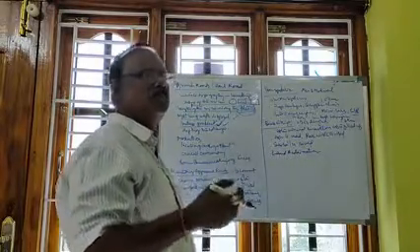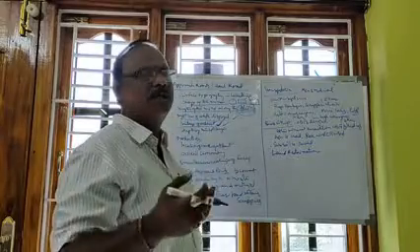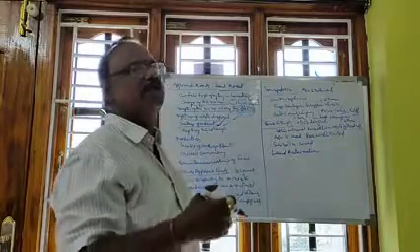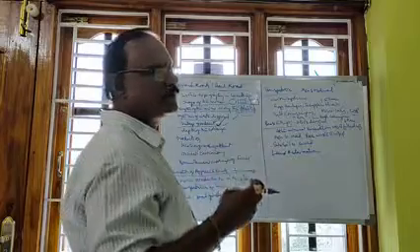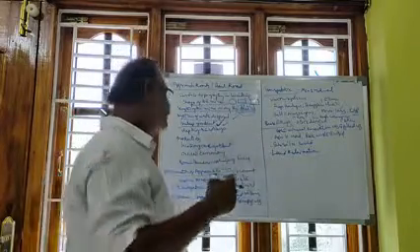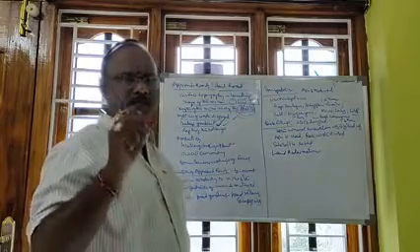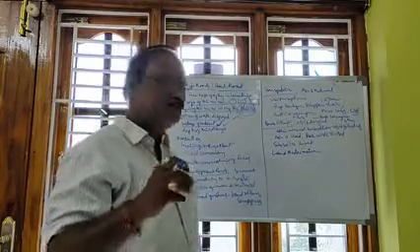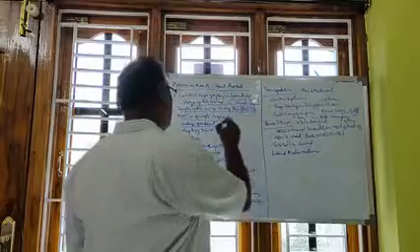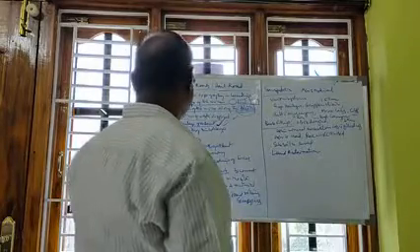It shall not be more than 1 in 8, because the transportation becomes very complex and complicated. Even heavy mechanization is not used there, so the gradient must be less than 1 in 10. So this is the haul gradient.